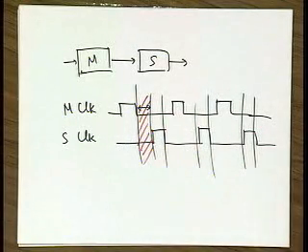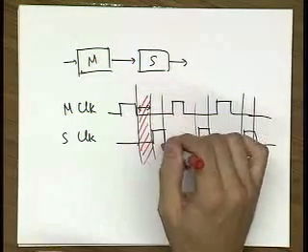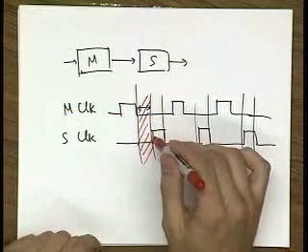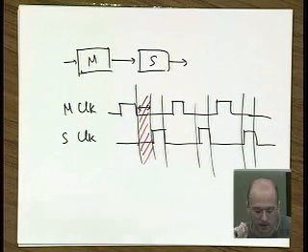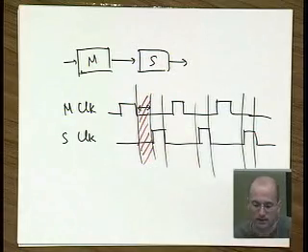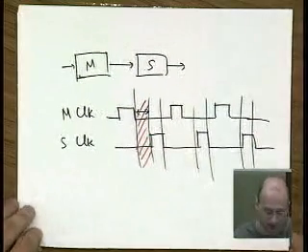You're basically making sure that you have a sufficiently wide margin so that your data does not contaminate your slave latch at the sampling edge. There are a number of other solutions. This is basically still the problem, and there are some good circuit topologies that you can use to avoid it, just by pure construction of your latch. By good latch design, you can avoid this problem intrinsically. And this is a pretty interesting thing to do.